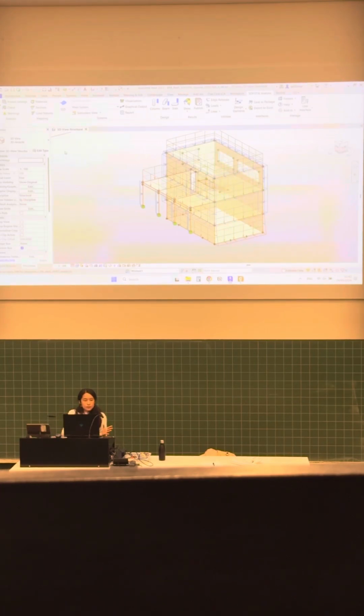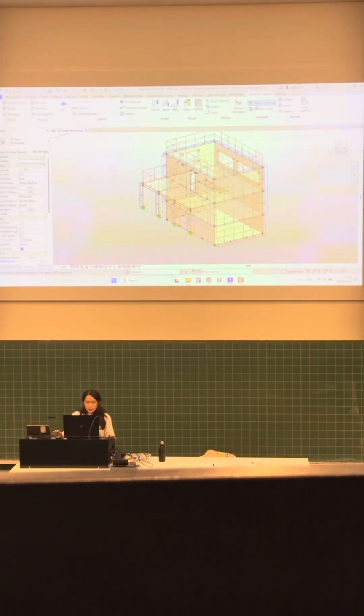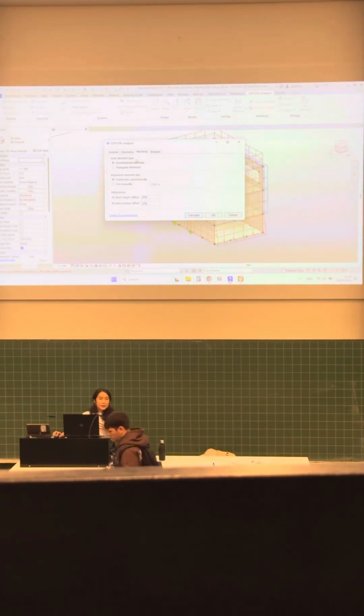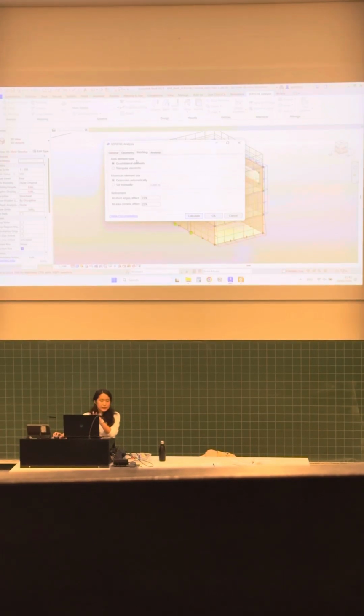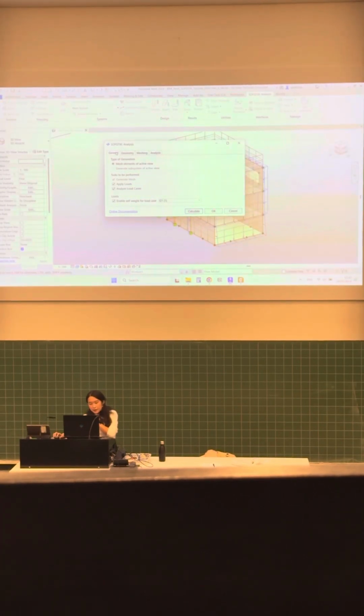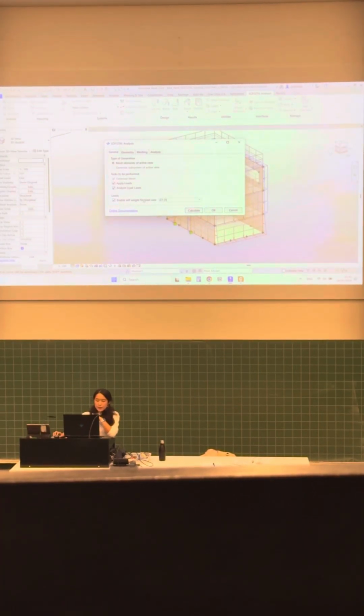And now we are ready with our model. When we check everything, we press start. A lot of people ask me, in your finite element model, in the future, you have to give what kind of FEM you want to use. So basically, this is a window where you specify everything regarding your analysis. For example, the meshing, applying the loads, also the load case, which will carry the self weight of the structure. For us it is G1.